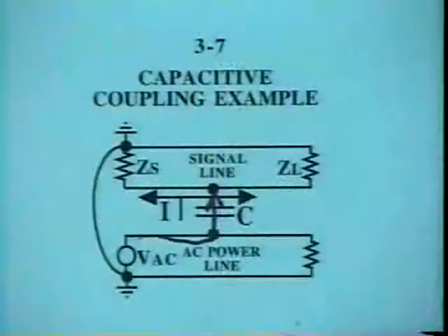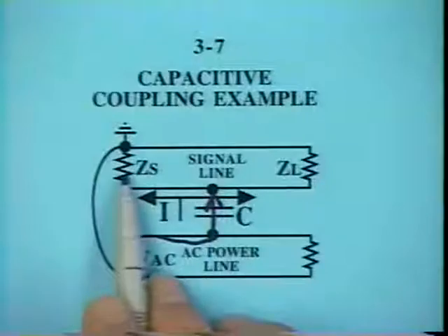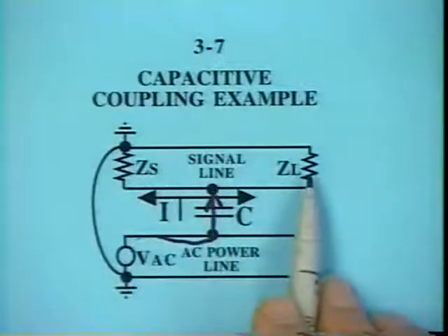Just concentrate on the impedance of the source and load end. At lower frequencies, say kilohertz frequencies, and for shorter cable runs, like cables of 50 feet or less, that's definitely true. Now you get up into the megahertz range or you get up to hundreds of feet of wiring, then we probably can't totally neglect the impedance properties of the wiring. But I would say as a very good first approximation, we can just ignore the properties of the wiring, concentrate on the source impedance and the load impedance.